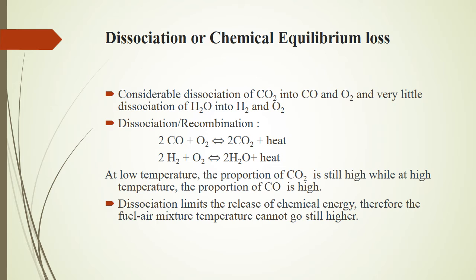Dissociation is the name given basically to the disintegration of burnt gases at high temperatures. Dissociation increases with the temperature. During dissociation, a considerable amount of heat is absorbed. This heat will be liberated when the elements recombine as the temperature falls.